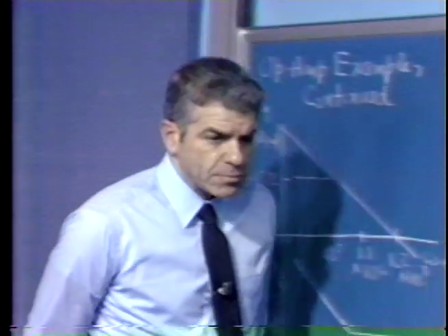The operational amplifier has finite output resistance, and consequently adding a capacitor to its output gives us an additional pole. And so now we have a two-pole kind of loop transmission. And certainly if the additional pole that we add occurs well below crossover, the stability of the amplifier is very severely compromised. I'd like to look at that.